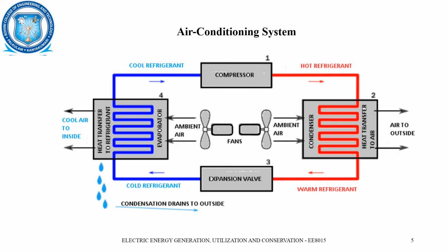Now we can see that the fans which are used here are ready to absorb the air into the room from the evaporator coil. The air from the atmosphere will be taken inside the evaporator, so that the colder refrigerant can cool the air. The air from the fan is sent inside the evaporator, where the coolness from this cold refrigerant will be transferred to the ambient air,